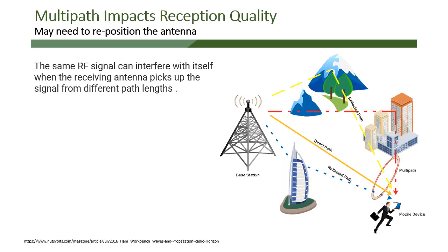And we talked a little bit about this, I think, before, but multipath signals, which are signals that are coming from the antenna, the transmitting antenna, to the receiver, but because of reflections and direct path, you can have all these signals hitting the receiving antenna at various times, and that's multipath. Well, look at these multipaths on the right. Notice that they're all taking a different path and they're all covering a different distance.